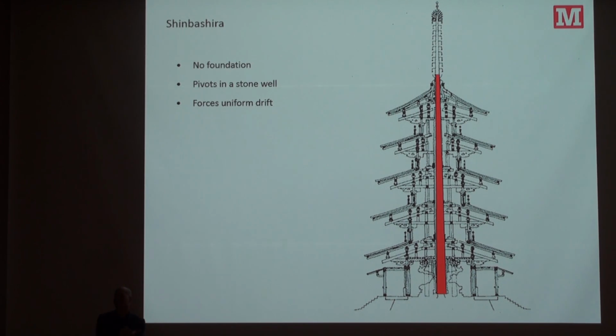It has no strength, but it's a circuit. So when the ground shakes and the bottom story tries to distort, the shimbashira engages it and makes the lower portion talk to the next level and the next level and the next level. When you see models of this, a temple will dance like a snake as the ground's moving, because there's this circuit going on.